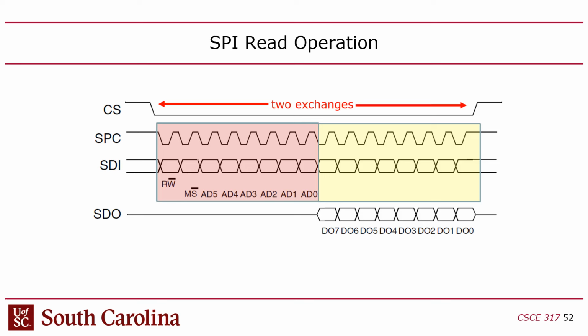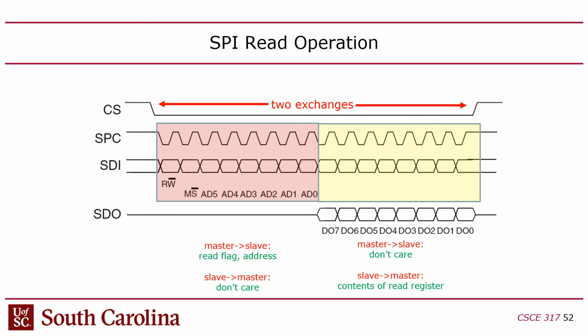And write operation, as you can see, is again very similar. You have the first bit indicating read or write, then you get the address where you want to write, and again here read is without the bar and write is with the bar. Basically, if it's 1, then it's read. If it's 0, then it's write. And then you have the data address where you want to read, and then you have the data output.